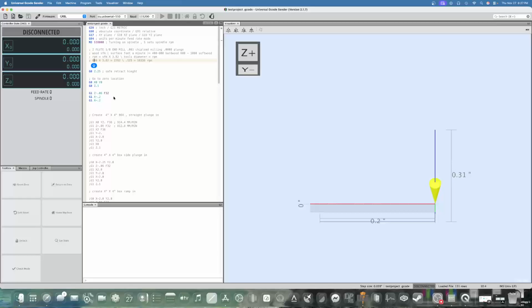Now for the actual feeding on this, one thing you can do when you come down here, if you put a comment in the front of it, see how it grays out. Well, now it's pretty much worthless. As far as the machine is concerned, it won't read it. I don't even think the G-code sender will send that data to it. It has to be highlighted, like your G0 here, X0, Y0. I have a couple different things set up ready to rock and roll here.